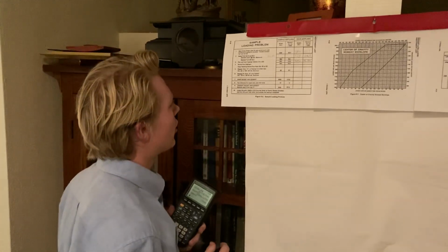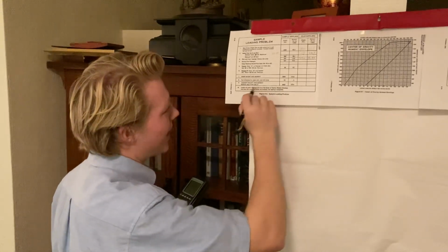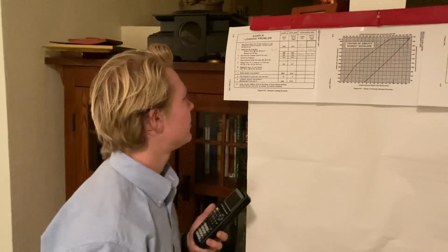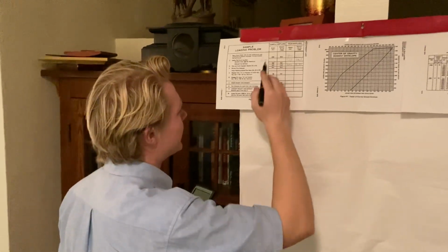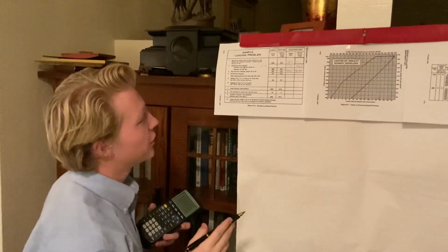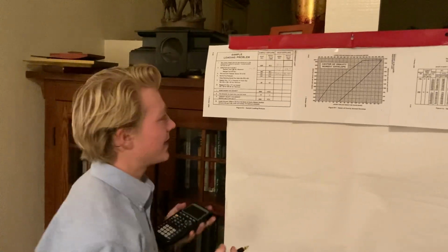This chart also gives us an allowance for engine start, taxi, and run up, saying that we're gonna burn that off before we take off. It gives us 10 pounds to burn, but we're gonna be conservative and say we're only gonna burn 6 pounds of fuel, which is about 1 gallon of gas.